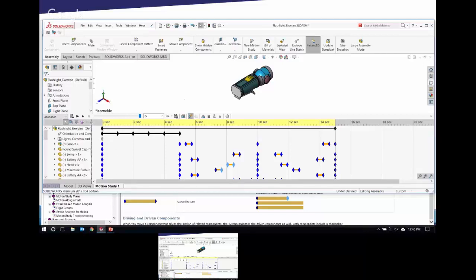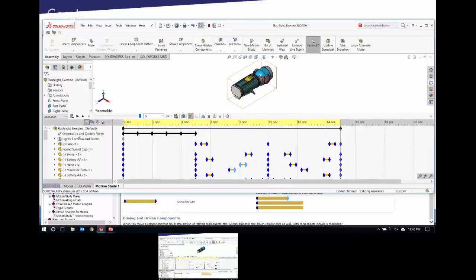So there's something that confuses a lot of people with the orientation and camera views, which is if I right-click on this, there are a couple of options here. One of them is to disable playback of the view keys. Remember, the view keys are just for the orientation. And then there's also an item which is disable view key creation. So this is how it'll show up by default, which is that the view key creation will be disabled, but the playback of the view keys will not be disabled.